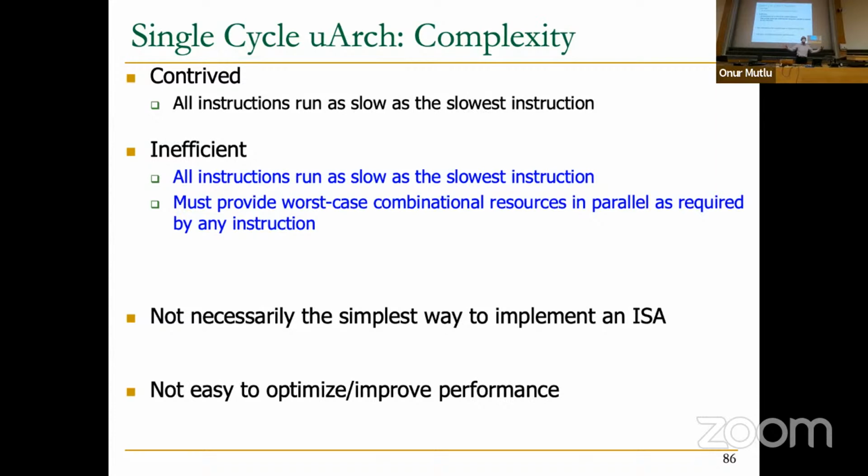Everything is combinational. But if you distributed the processing over multiple cycles, you could have just one ALU. In this cycle, I'm going to increment PC+4 using that ALU. In the next cycle, I'm going to use it to calculate the address. In the next cycle, I'm going to use it to add multiple operands.